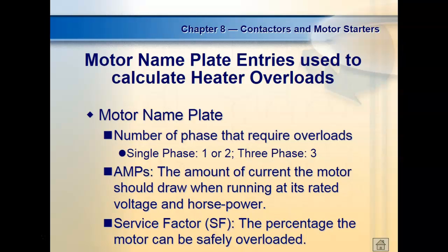Okay. Then we have something called a service factor. What's the service factor? Yeah, so ours has a service factor of 1. What does that mean? It means you can't overload it, right? Can't overload it. So we definitely couldn't plug it. Y'all know what plugging a motor is? Plugging a motor is when you change directions without letting the motor come to a stop.